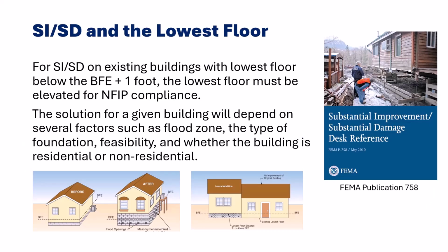Administration of the SI and SD requirements is an important local role of the floodplain administrator. The solution for a given existing building will depend on several factors such as flood zone, the type of foundation, how feasible it is to elevate or mitigate, and whether the building is residential or non-residential, where floodproofing might be an option.